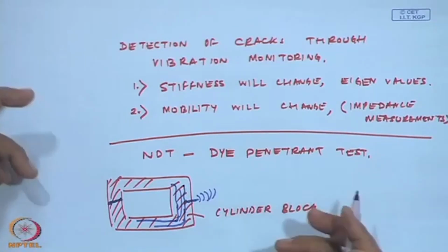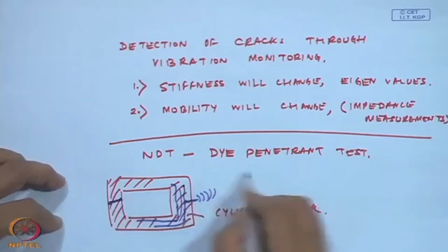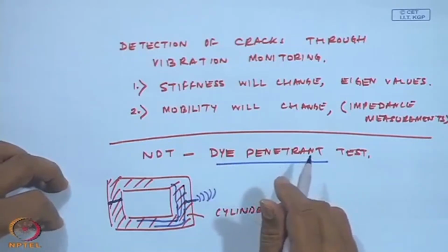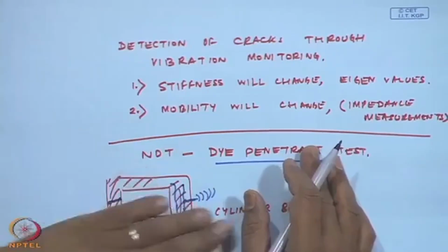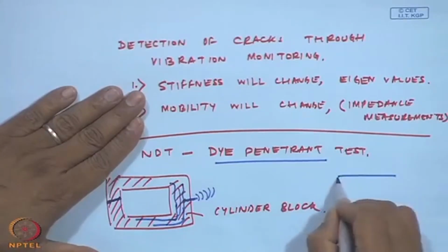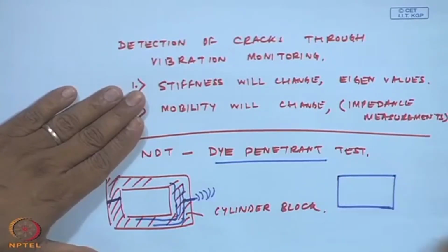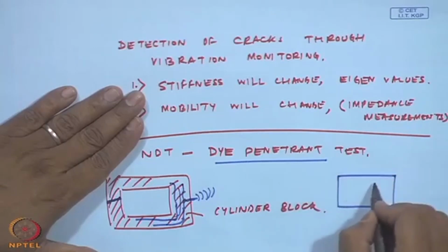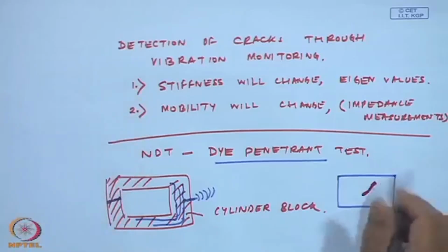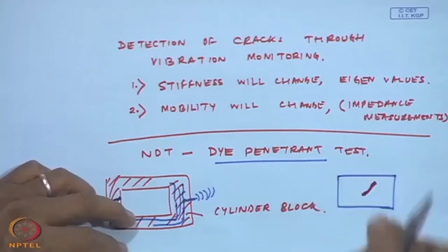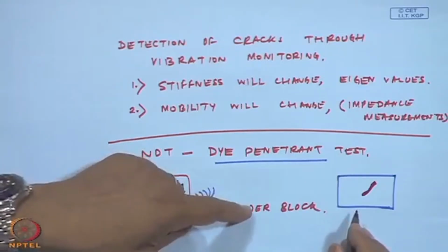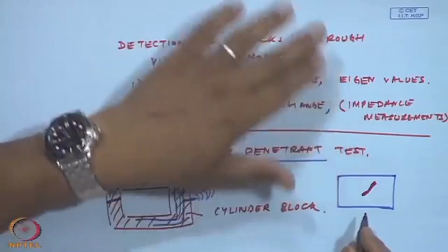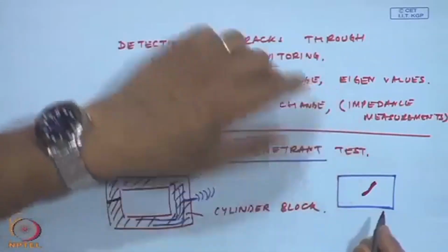Okay. So, how do you detect such kind of cracks? So, that is why they do what is known as a dye penetrant test. After the castings are done, they smear it with a dye, okay, and then rub it off. And if the crack is there, after you have smeared the surface, the dye will make a mark, ooze out and clearly show that a crack has occurred, just looking at the dye. And this dye could be not visible to the naked eye, it could have a fluorescent lamp where the dye is going to glow, and then you can clearly see that a crack has occurred.